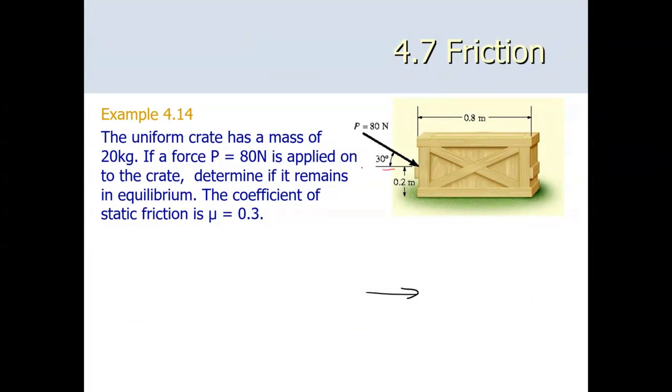All right, so this force, I'm breaking that into two forces. That is Px, this one is Py. All right, and making a free body diagram, I have to release this from the surface. So that is the center of gravity. So the weight is exerting here, and I know that the friction is tangent to here, but where should I place the normal force? Should I place my normal force here, or should I place it here or to the left? Which one? Where should I put N?